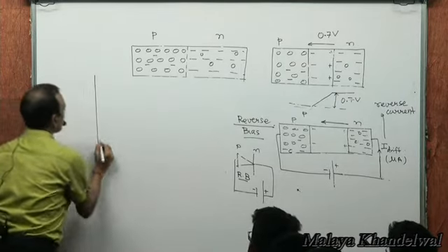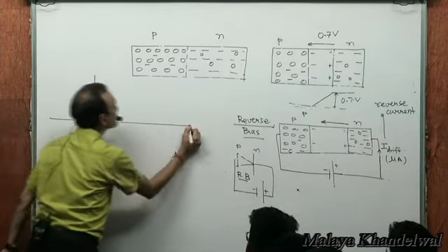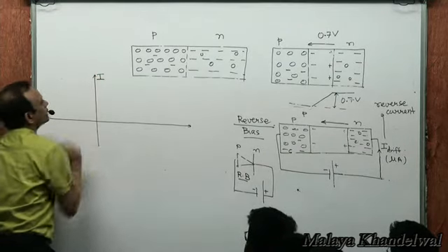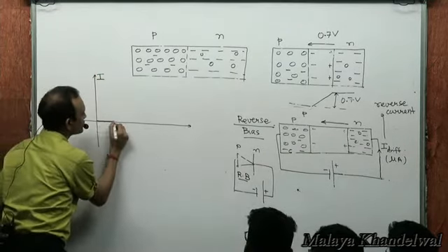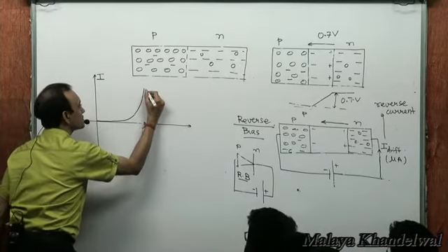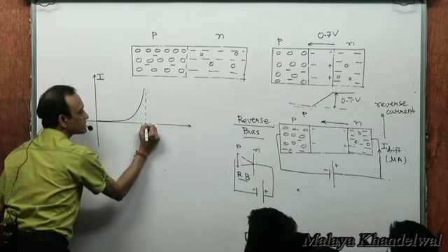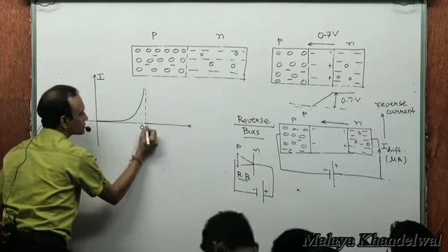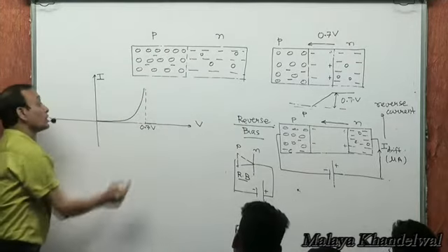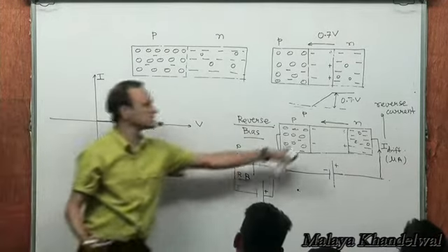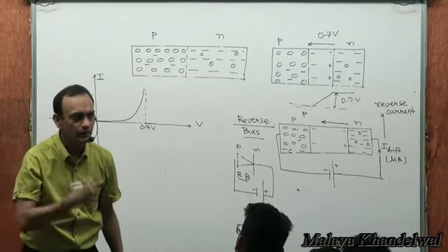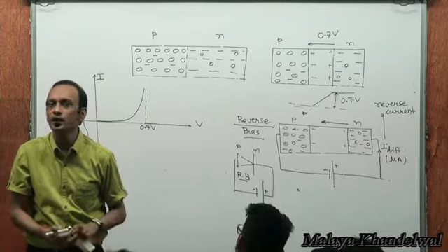So what really transpired was, in the forward bias, we saw the current versus applied voltage being something like this. There's a sudden surge of current at cut-in voltage. Right? This is what we saw in forward bias. In reverse bias, since the current is in the opposite direction, it's a reverse current, we take those currents as negative. Right? It's a very small amount of current.